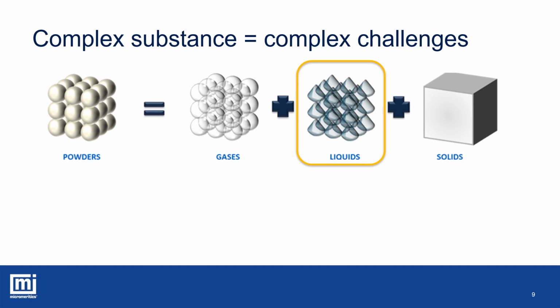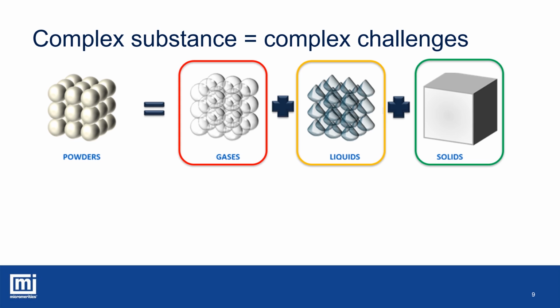So some of our issues with process robustness are around liquid content. Quantity is at least measurable, but the bigger issue is liquid distribution within the powder, as this is not measurable. So I've highlighted liquids in yellow to signify that these are an area of challenge. Gases are in red, as this is an even more challenging issue, as these are hard to quantify both in terms of amount but also in distribution through the powder, and both of these can have pretty massive effects on powder performance. So, enough bad news.